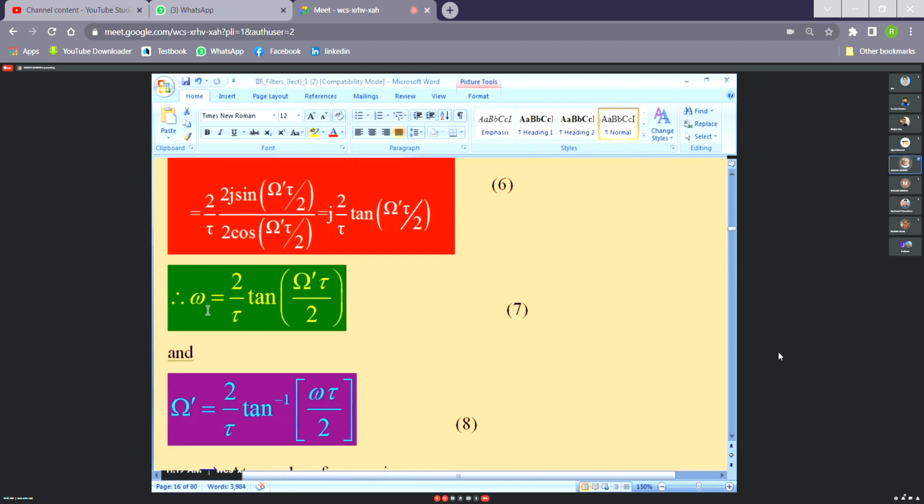In the course of applying bilinear transformation, distortion will take place in accordance with 8, just the reverse distortion. So the pre-introduced distortion and the distortion due to bilinear transformation nullify each other at frequencies close to the critical frequencies. So that is the idea involved.